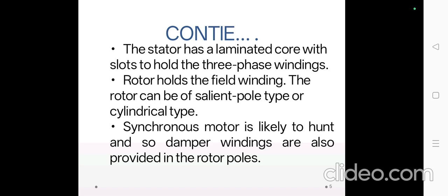The laminated construction is basically to keep down the eddy current losses. Generally, the choice of material is steel to keep down the hysteresis losses. The core is fabricated in a frame made of steel plates. The core has slots on its periphery for housing the armature conductors. The frame does not carry any flux and serves as a support to the core. Ventilation is maintained with the help of holes cast in the frame.